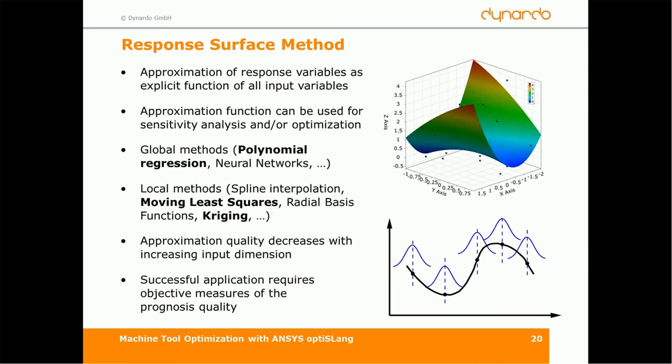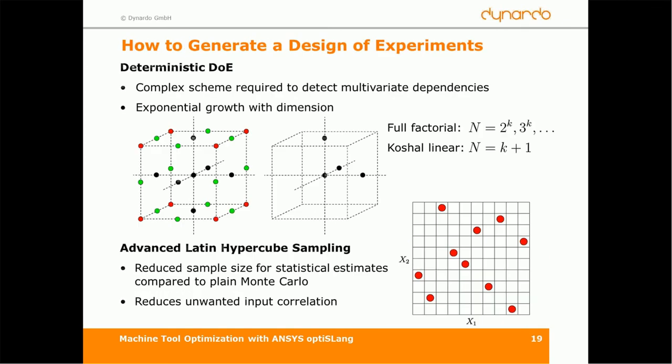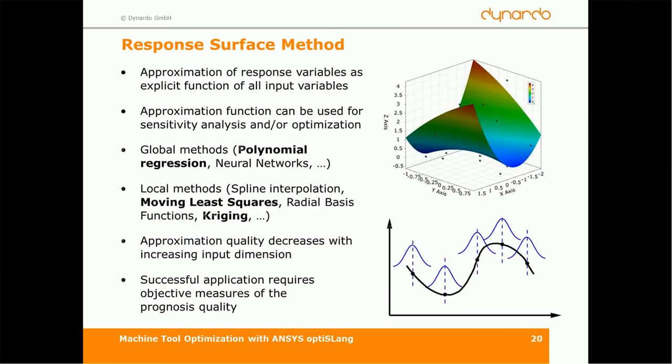What helps for that? Usually, a response surface method is a quite suitable approach for that. We can build up a so-called Metamodel, a mathematical surrogate function, in order to describe the relation between the input parameters and a response. We just take the points generated before by the design of experiment scheme, and we try to approximate the behavior between a certain response and the individual input parameters.